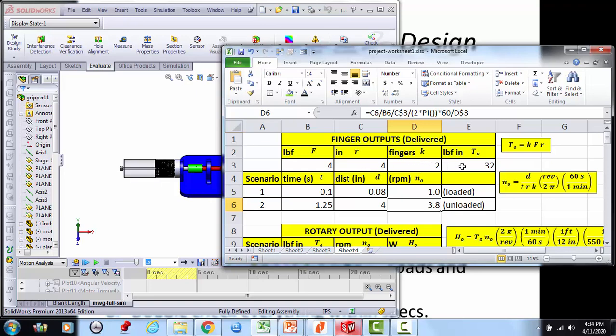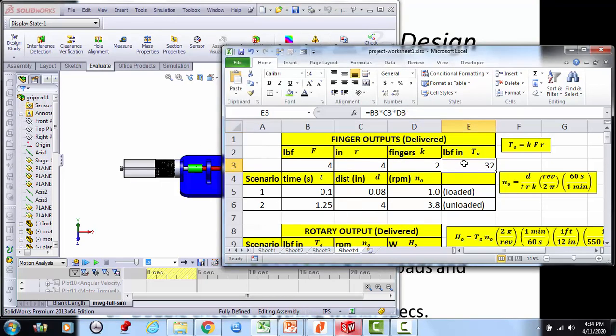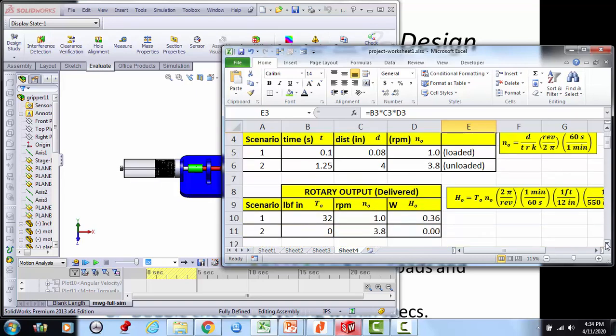And of course we have the two fingers, so the output torque on each of those worm gears is going to be simply the force times the radius, and then since there are two fingers, we're going to have 2 of those applied to the worm. So we're transitioning really from having a force to having a rotation. So we're almost where we want to be.